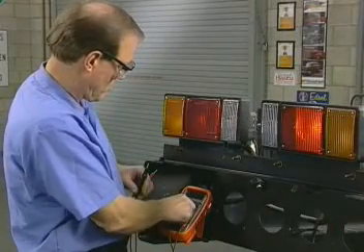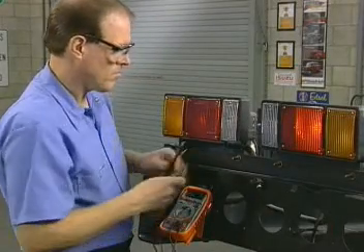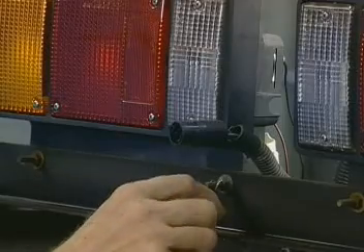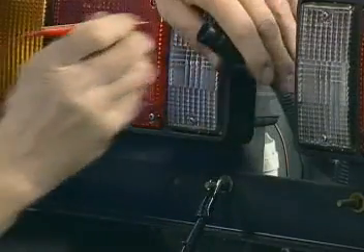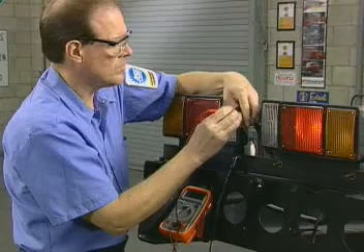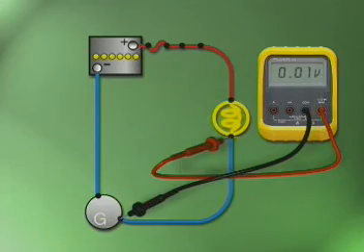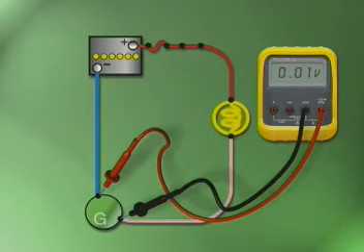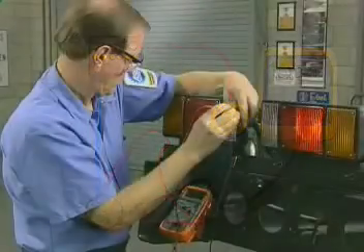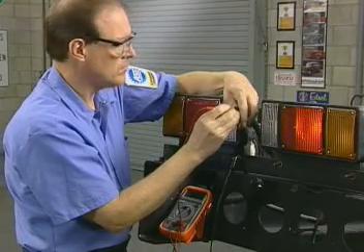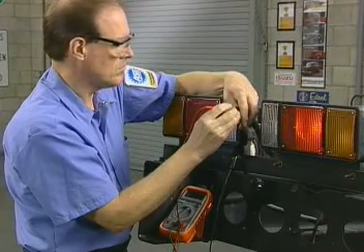With current flowing through the circuit, set the meter to the appropriate volt scale within the range of the maximum readings you expect to find. Then measure each segment of the circuit by moving the leads to measure voltage across each switch, load, length of wire, and finally the ground. If the meter reading shows a negative voltage, then reverse the probe connections.